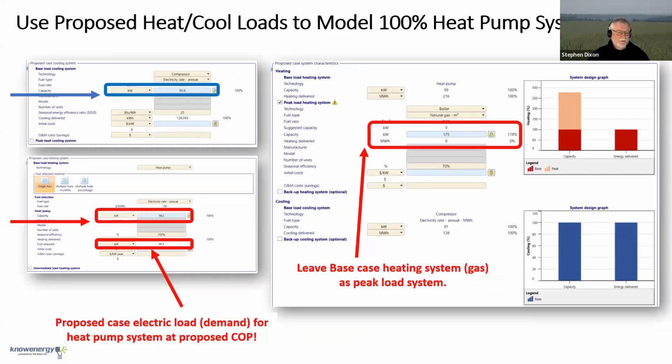So 98.5 multiplied by 3.4 will give you the BTU per hour, divided by 12 is going to give you the tons. So you could specify this as tons as well. But to be consistent with all these, we're just going to leave the units of load at kilowatts. But that's not electrical load at this point. This is actually the thermal load, whether it's for heating or cooling.